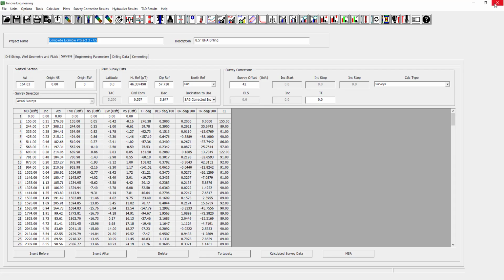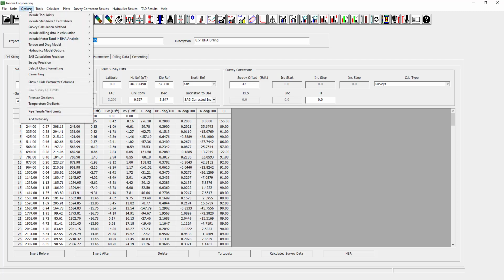The colors and line styles that you choose in the chart defaults dialog will only apply if you have the other two options turned on. So that's the auto chart colors option and the auto chart line styles option. When these are set to yes, the program will use whatever you set up in the chart defaults dialog. But if you set these to no, then the chart will use random colors and random line styles.